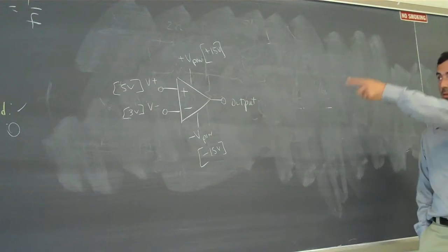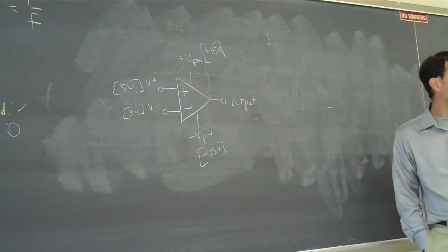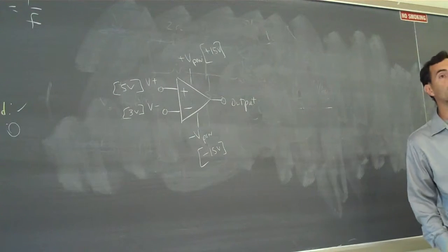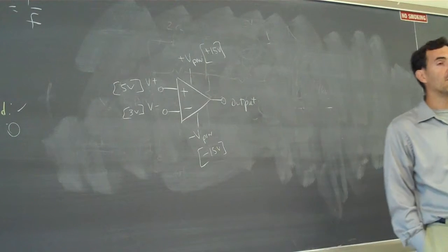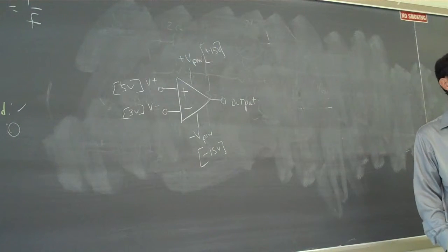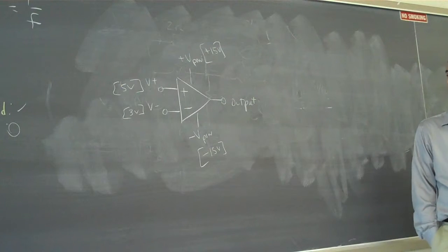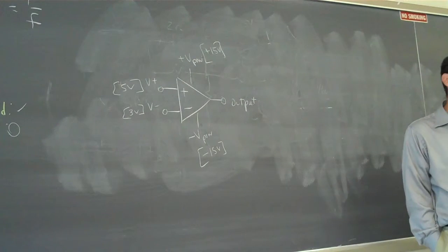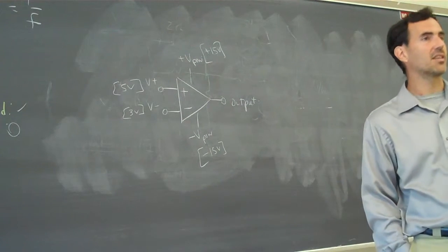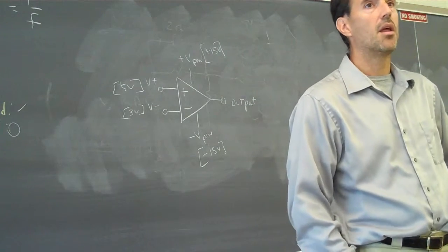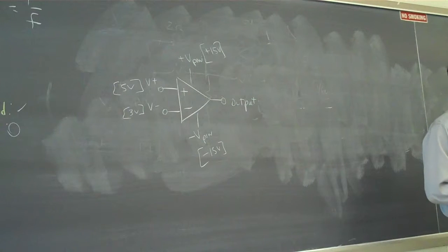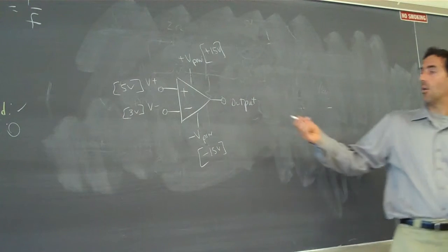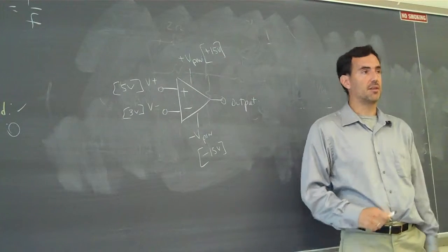30, good guess. You're looking at the difference between the two. And Ryan's saying 15. He's saying the most positive voltage it can maybe produce is 15. Both good guesses. Ryan's correct. So it will get to about 15 volts. Now, it won't even quite get to 15. It'll get to like 14. But unless I specify otherwise, assume on an exam or a quiz or a Smith, which we'll do in a moment, that it will just get up to the 15.